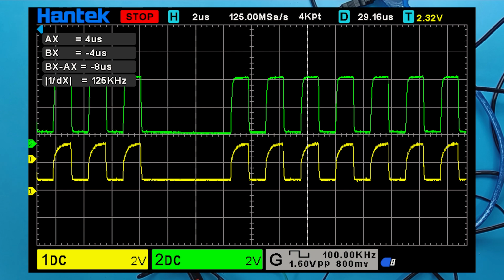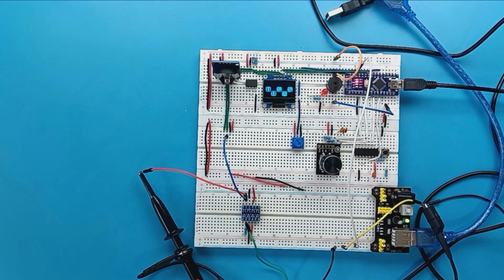I might consider lowering the pull-up resistors to try to overcome that rising edge. But that's for another day. Today I'm going to leave the video there. Hopefully you get to see and understand exactly what a logic level converter chip does.